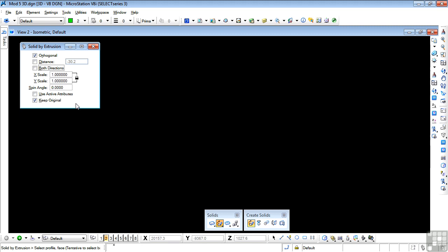If you do try to extrude a set of separate elements, you'll likely see a warning message advising that your action may result in overlapping geometry. This is not permitted, and the extrusion will not be completed. Thirdly, after extruding a profile, you may not want to see or even keep the original profile element. There are several ways of achieving this. You can turn that option off in the Tool Settings window, as we just saw, or you can draw the profile on a different level from the extrusion, or use a construction class element as the profile.